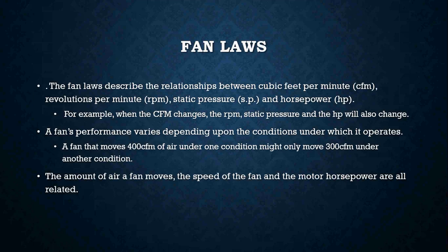Okay, next that we're going to have to think about, and it's honestly not really taught so much in technical schools, is fan laws. Fan laws really help a mechanic in understanding the relationship between the blower that they're working on and airflow.